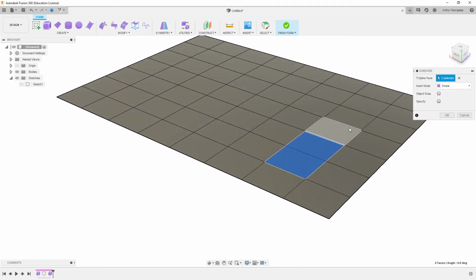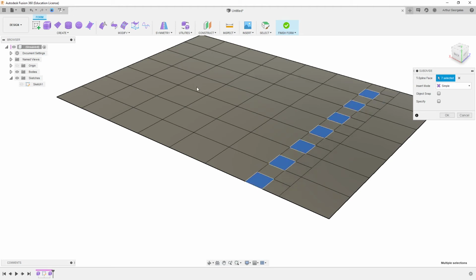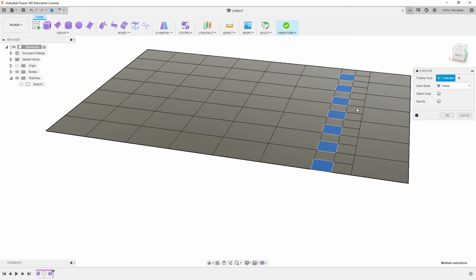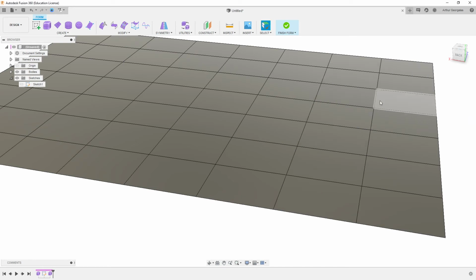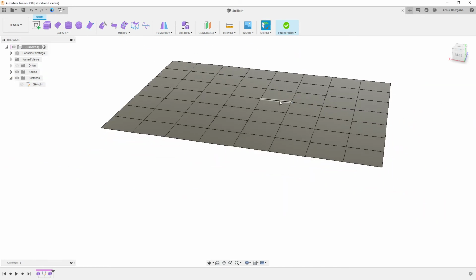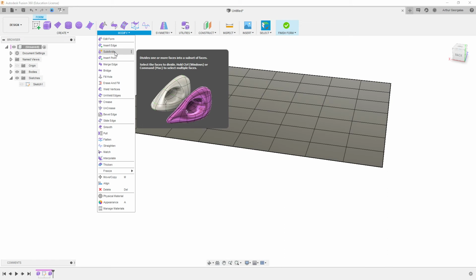To increase the selection of faces, you have to hold control, because it won't let you just click another one. But again, this brings in that problem of these faces not connecting out to anything, so they're going to start to blur and get really weird transitions over time. So I generally avoid using Subdivide.